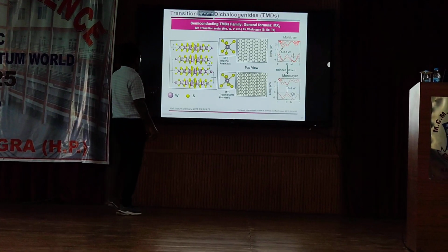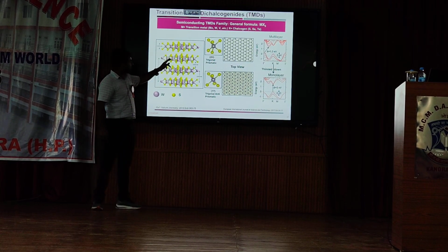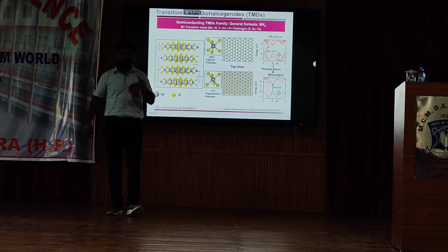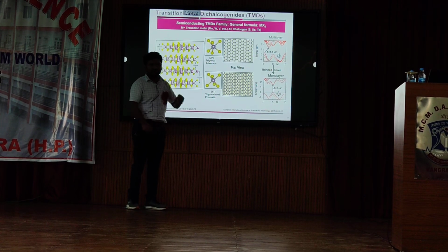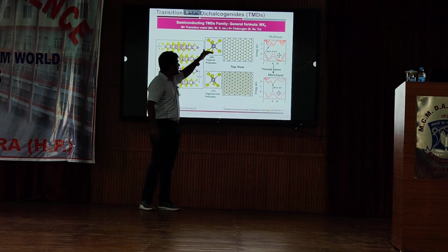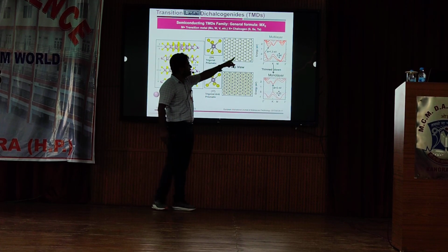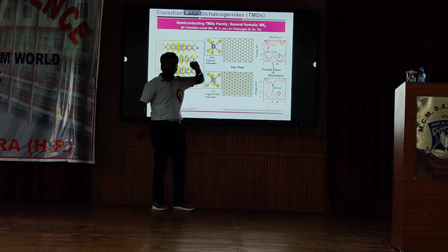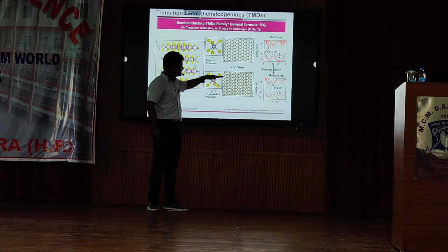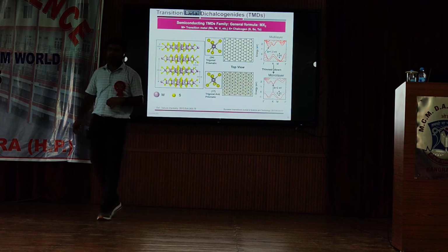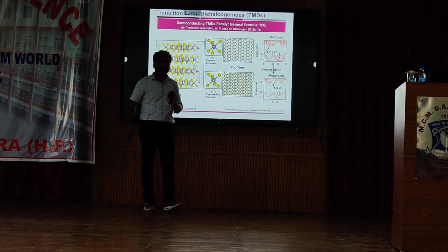So this is not an actual 2D material. If we take the single layer of TMD, it is a kind of quasi 2D material, because there are 3 layers. Generally there are 2 polymorphs of transition metal dichalcogenide. One is the 2H, which is semiconducting in nature, that is trigonal prismatic, and another one is the trigonal anti-prismatic. You just rotate from the center. So this is the trigonal anti-prismatic. If you see this polymorph from the top, it looks like a hexagon, similar to graphene. But this is not graphene, because in alternate atoms you are seeing, in graphene every atom is carbon. Here one atom is transition metal, another is the chalcogen, right? It is different from graphene. And the 1T phase of transition metal dichalcogenide looks like 2 interpenetrating hexagons. The 1T phase is metallic and the 2H phase is semiconducting. Our interest is in semiconducting, because we want to develop a 2D field effect transistor.